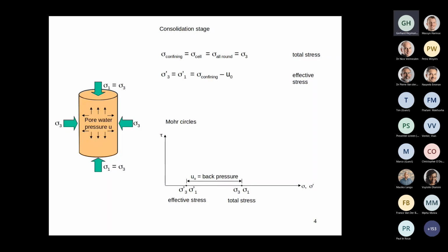If you know how to plot your Mohr circles and your stress paths, regardless of whatever the lab sends you, go develop your own spreadsheets, plot your own stress paths, and determine your own shear strength parameters. That process allows you to develop a much better understanding of the behavior of your material. Okay, so there's my first little sermon if you're one of the young engineers. These are simple equations. Use them to develop your own spreadsheets.